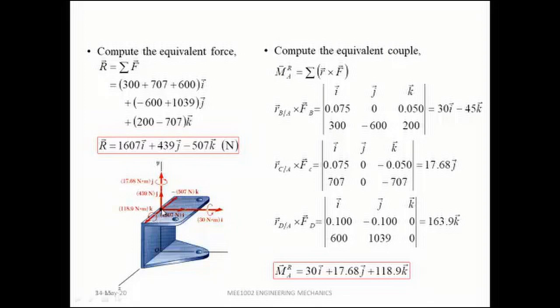So we moved all the forces to A and we introduced the moment, but it is represented in terms of rectangular coordinates. So if at all to represent R vector, it will have a particular direction. We'll put that, and all these three vectors resultant will be in one particular direction. So that way the net effect can be represented. So reduction of all the forces to A without affecting the net effect is understood.